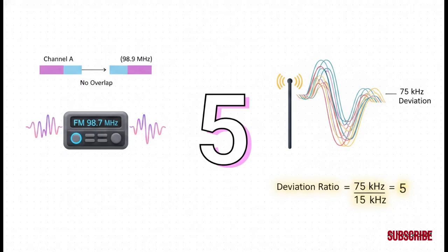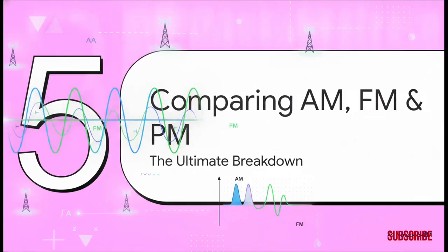Let's apply this to the real world of standard FM broadcasting. Yeah, the exact kind you listen to in your car. Standard FM has a legally mandated maximum deviation of 75 kHz and a maximum modulating frequency for human hearing of 15 kHz. If you divide 75 by 15, we get a fixed deviation ratio of exactly 5. This standardized number is the magic rule that ensures every FM radio station fits neatly next to each other on the dial without overlapping.